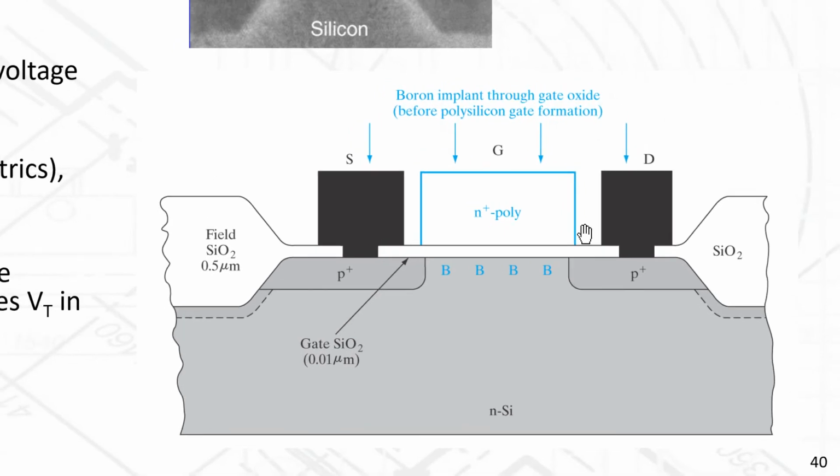Just look at the center part here. In the center part, what you're seeing is a typical structure. You have your source, gate, drain, your channel underneath here. By the way, this is an N-type substrate, and this is a P-type source and drain. Does anyone know what type of device this is? Is it NMOS or PMOS? PMOS. It's a PMOS device.